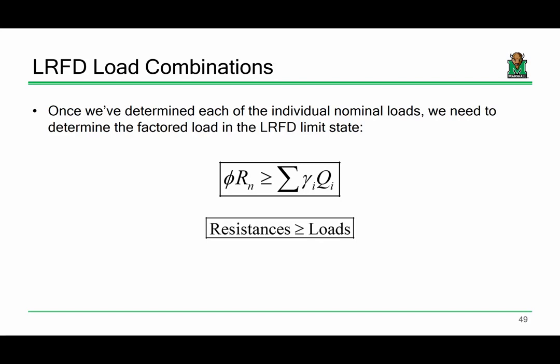See, let's take dead loads and live loads. I think I'm probably going to be a little bit better at estimating dead loads than I am live loads. I mean, if I wanted to estimate the dead loads associated with this floor system above me, really all I need is a calculator and the plans for the building. Because what I can do is say, okay, here's this drop ceiling, here's how much it weighs, here's the mechanical, electrical, plumbing, here's how much it weighs, here's the beams, here's the slabs, here's the carpet and all that.